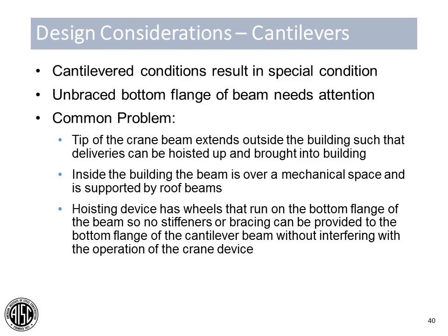Cantilevers are also a special condition that are very common with really any type of crane system. You may see these where the tips of crane runway girders extend outside of a building so you can pick up deliveries off of the bed of a truck and hoist them into the building, or within a building where you're trying to cantilever your crane system over perhaps a mechanical piece of equipment or a specific area where our friends, the architects, are not allowing us to put any of our superstructure.